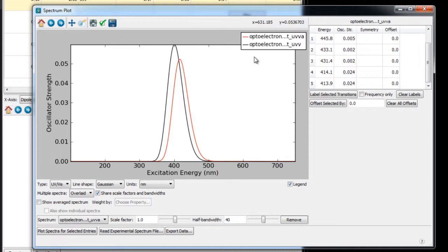This is useful as it is desirable that charge transport materials not absorb in regions of the spectrum where the pixel is emitting light. Because photons of light can go through a number of internal reflections before exiting the device, even a small amount of absorption in the wrong region of the spectrum can lead to a dramatic decrease in the light outcoupling efficiency of the device. So, being able to compare predicted spectra, as shown here, allows for the rational design of materials with less absorption in the emission window.